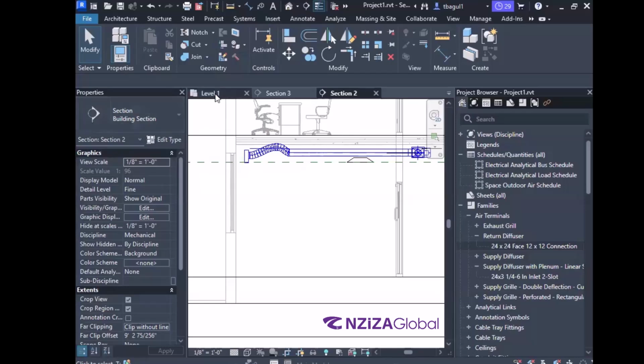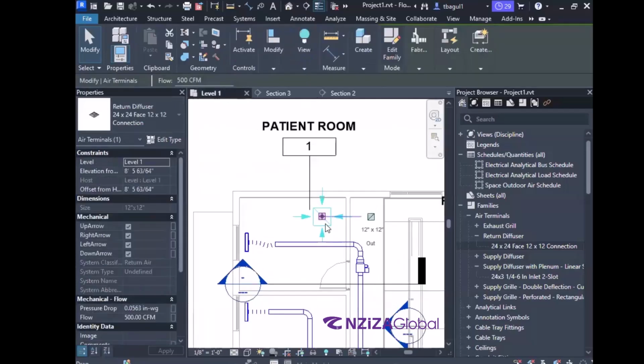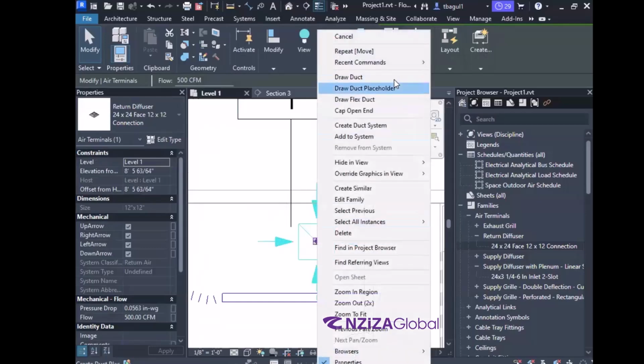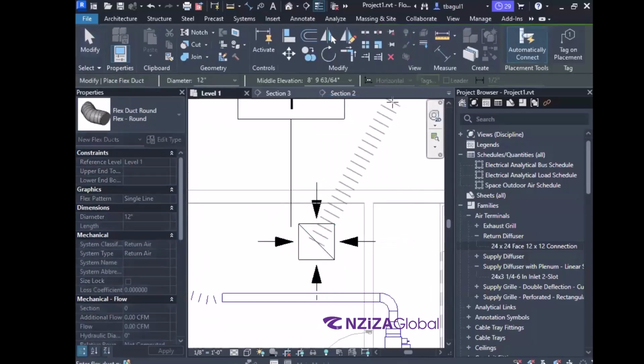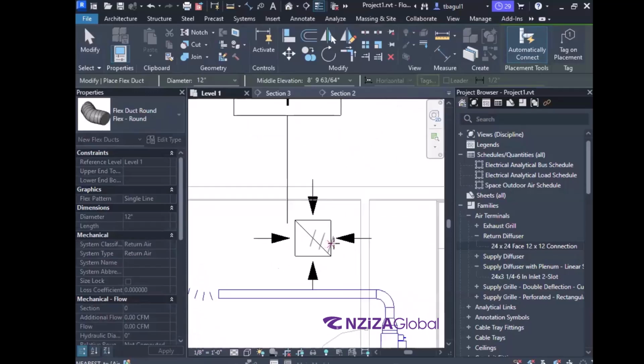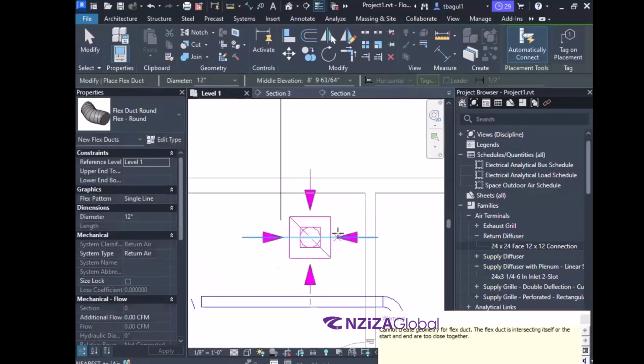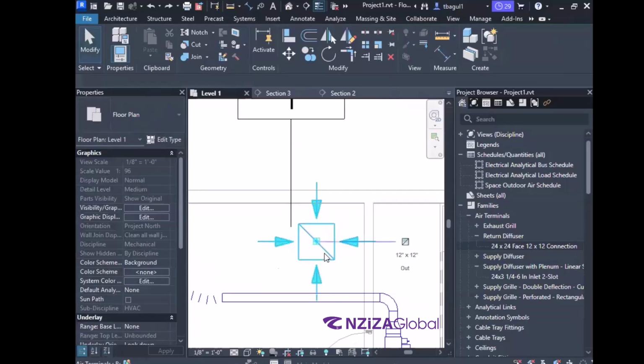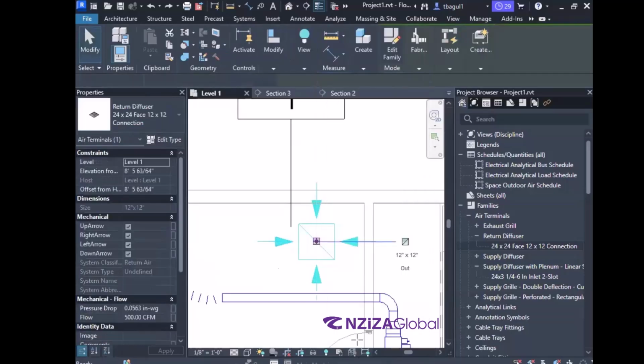Yes. All right. So now what we are going to do is, first, we'll make sure that we start drawing a small flex duct. Again, don't make this duct very lengthy, maximum 5 feet. And on return, most of the times you will not find that big of a flex duct as compared to this one. So it is fine if you take it to a small length. Okay. So make sure that the duct basically comes a bit out of that diffuser. Yes.